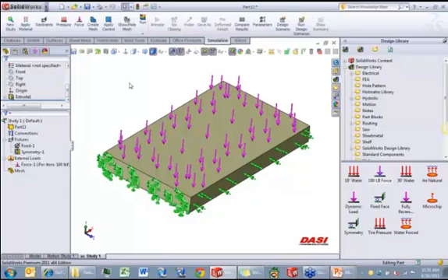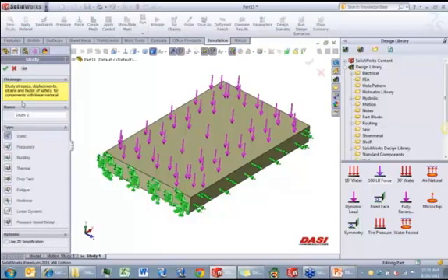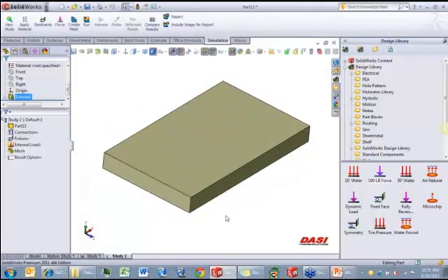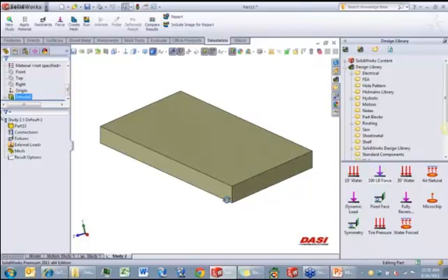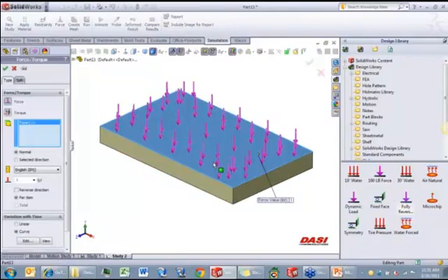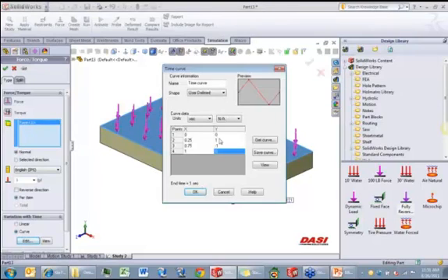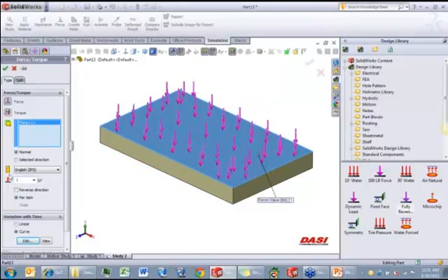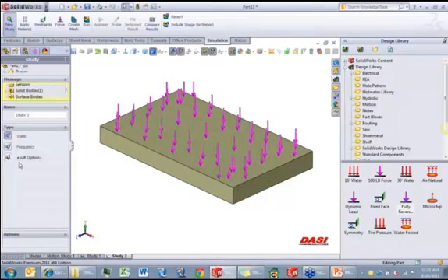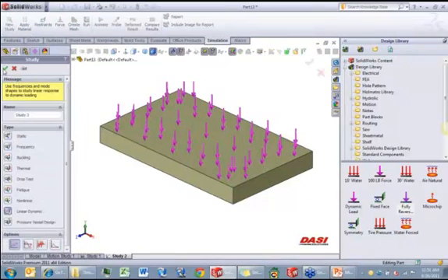There's other reasons you might use this too. If I create a nonlinear study, not everybody has nonlinear capability, but I can drag and drop in a fully reversed load. The benefit here is the timetable is already set up for applying the load and fully reversing it. I just need to put in the magnitude, the weight, or even a dynamic study, a linear dynamic one.